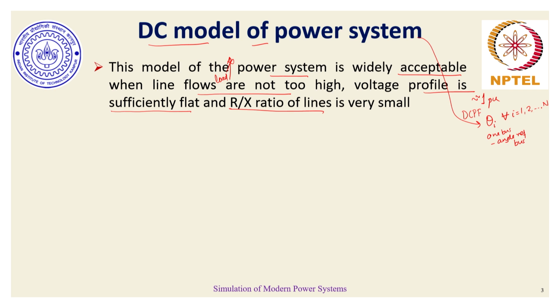Please have patience. The angle reference bus, whose angle we typically choose as 0 radians or 0 degrees, we will stick to the 0 radian part. Radian is the default electrical engineering convention for voltage phasors and other phasor quantities. With degrees there could be mistakes.